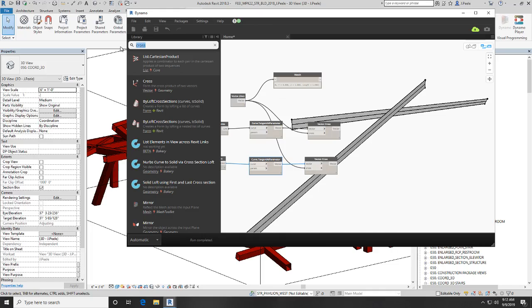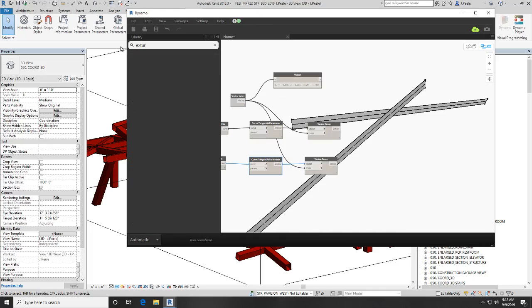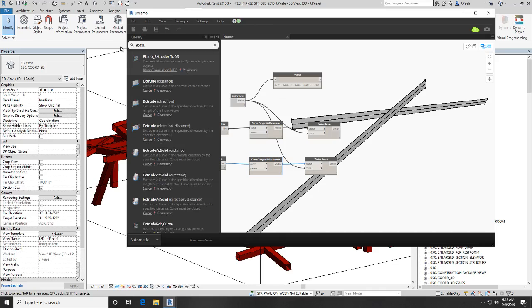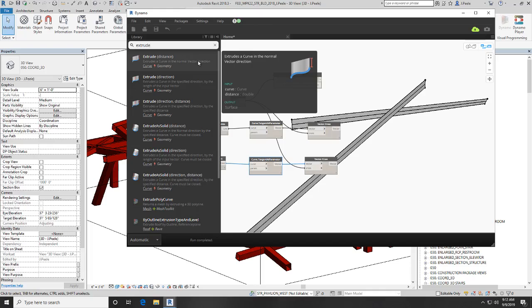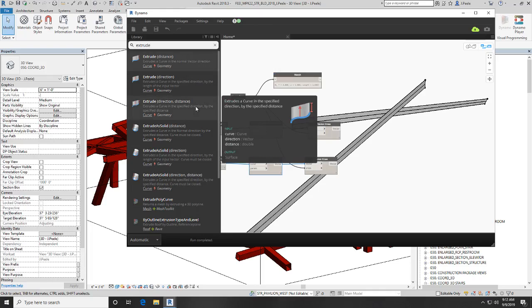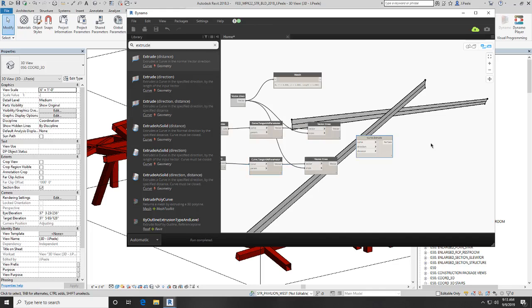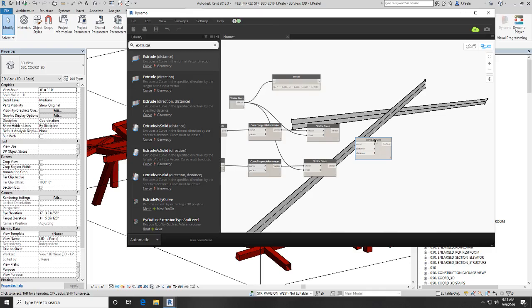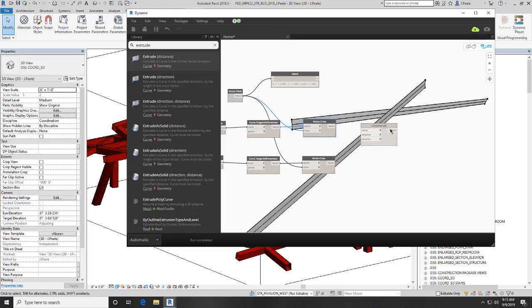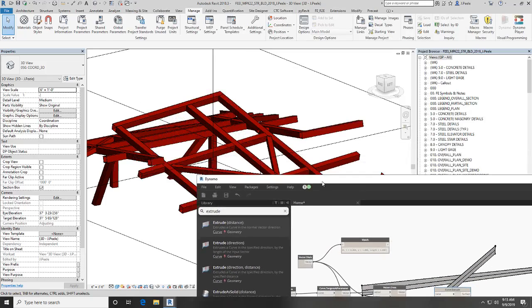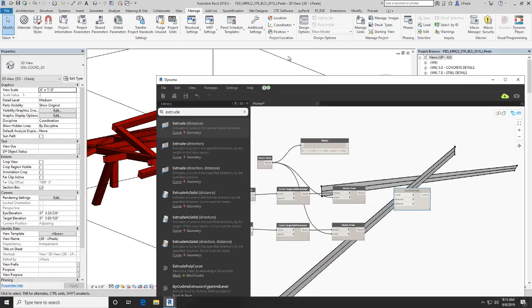But what we can do is extrude our curve, and we're going to do the direction and distance, because if we simply did a regular distance, it would be the distance of the cross product vector, which, I believe, is normalized to 1, and we don't necessarily want a 1 foot extrusion because we're not sure if these two are 1 foot away or more.